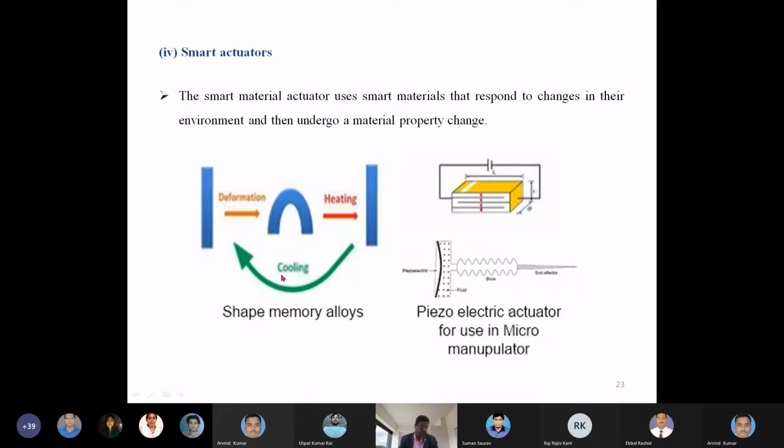It is programmed as a semicircle, and this is very commonly used in dentistry, orthodontics, and other tensioning devices when we want to apply it. So these materials are used as actuators. And this is a piezoelectric actuator, where piezo material is used as a semiconductor thin film. There will be a semiconductor film at the top as well as the bottom. Whenever an electric voltage is applied across the conducting film, the crystal expands.